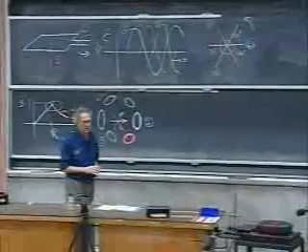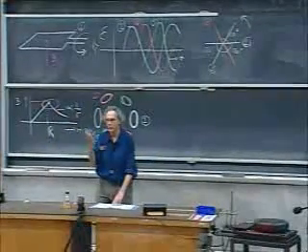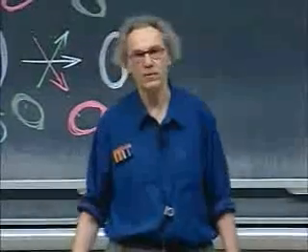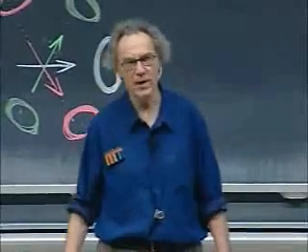And so it starts to torque up this conducting sphere. And all the time there will be eddy currents because the magnetic field keeps going around. And so you're going to get a torque which will always be in the same direction, and this conducting object will now start to rotate, and we call that an induction motor. Induction motors have no brushes.